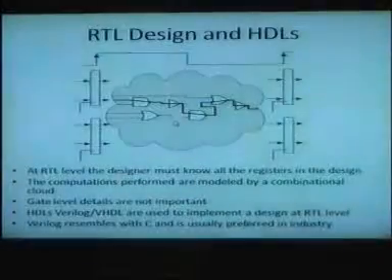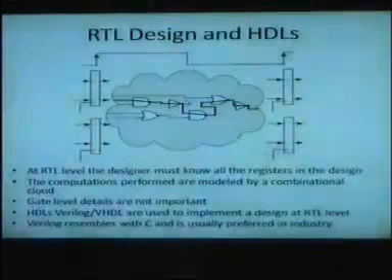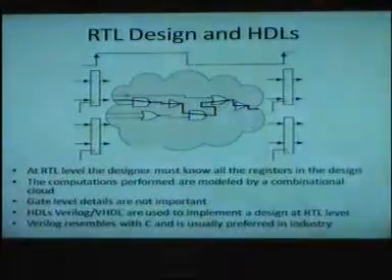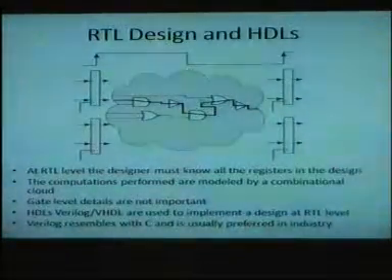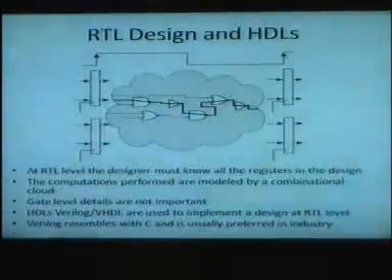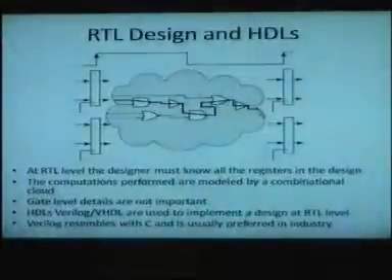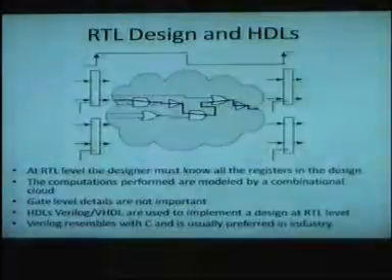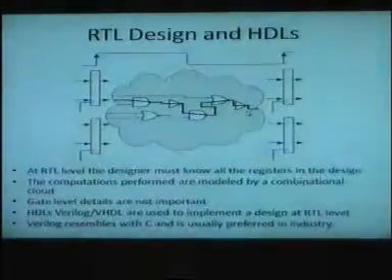And what happens usually, there are billions of paths in your design. There are paths which are shorter. For example, you trace this path, it has 1 gate and 2 gates. So a signal traveling on this path will settle here quicker than a signal which has to pass through 1 gate, 2 gate, 3 gate, 4 gate, 5 gate. So it will take more time.